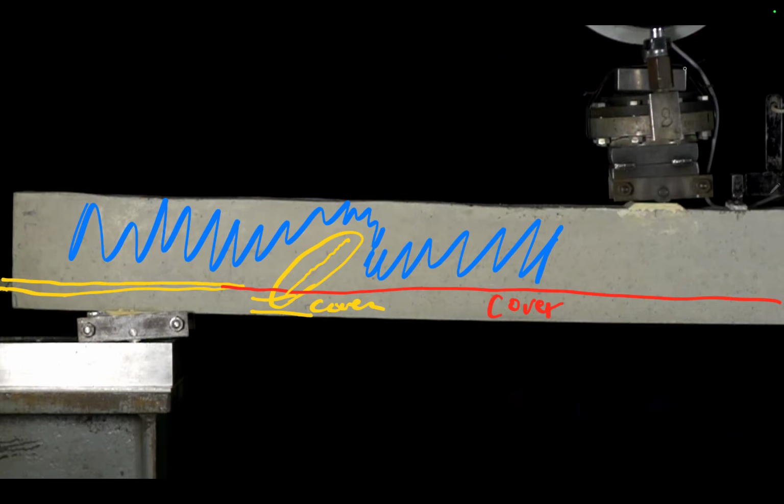And as you keep applying loads down, deflection down, what's going to happen? The crack will develop even larger. It will continue until it's fully fractured. Upon fully fracturing, at the same time, the stresses are being taken on by the rebar. I've shown you this in real life, a piece of concrete routed out where rebar is in the concrete. This is the top view, I think we're going to go with.